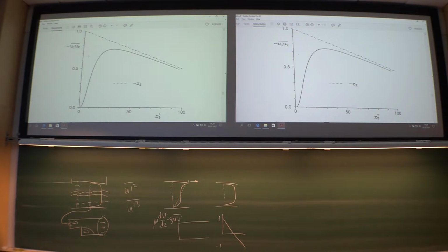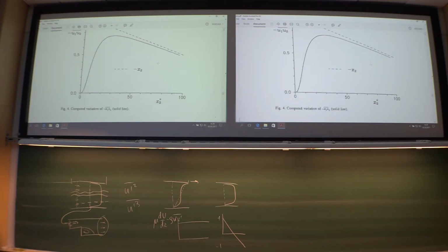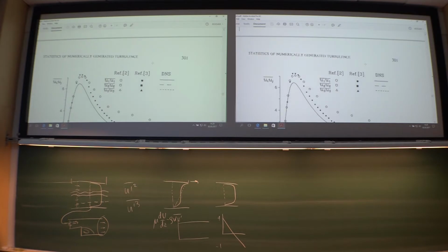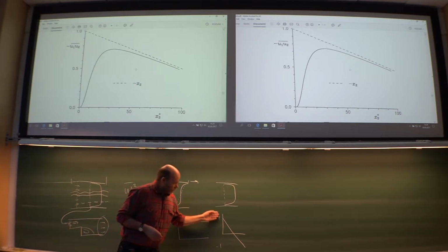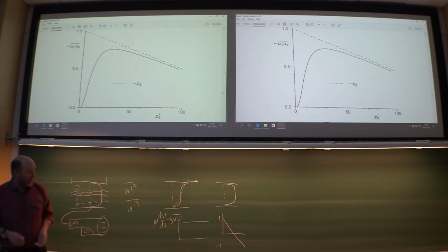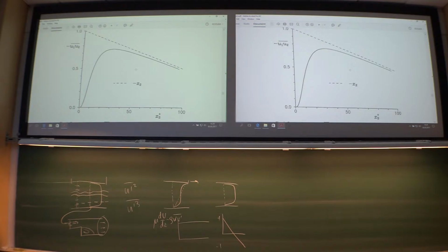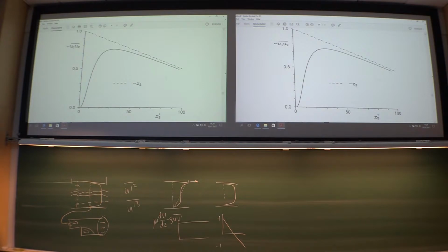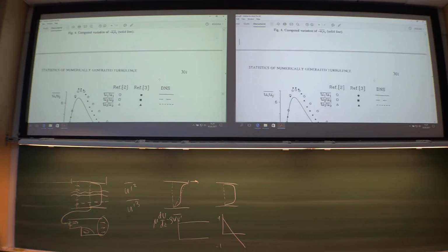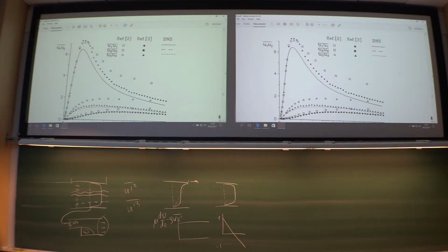So the dashed line is actually the sum of the viscous and the turbulent shear. You can try to set up the Navier-Stokes equations, simplify them with the Reynolds equations and see how far you can get. Then you can see that the total shear has to be a straight line, and for a Couette flow, it has to be constant. This can be used as a control also, to check that you have correct or adequate statistics.